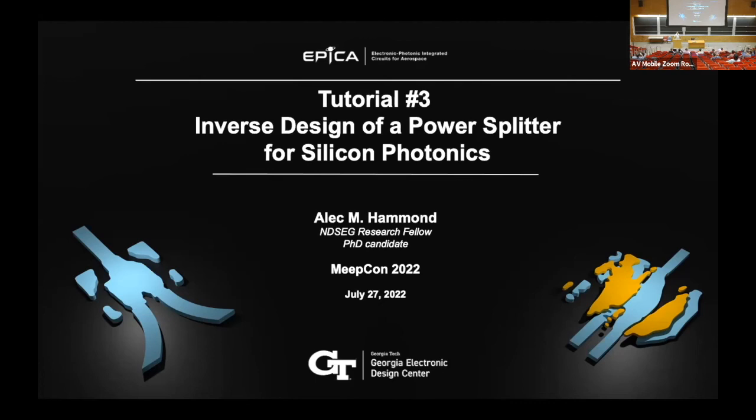From your experience designing these kinds of devices, is there some upper limit on dimensions where it gets unwieldy or takes too long in terms of simulation time? What have you found? I've easily done, I wouldn't say easily, after about 4 days of computation, I was able to do 25 lambda in each dimension. But I've also lately been able to do about 50 lambda in each dimension on our clusters at Georgia Tech. And you could probably do more depending on how much you're willing to wait. But 50 lambda in each dimension is pretty large for FDTD.